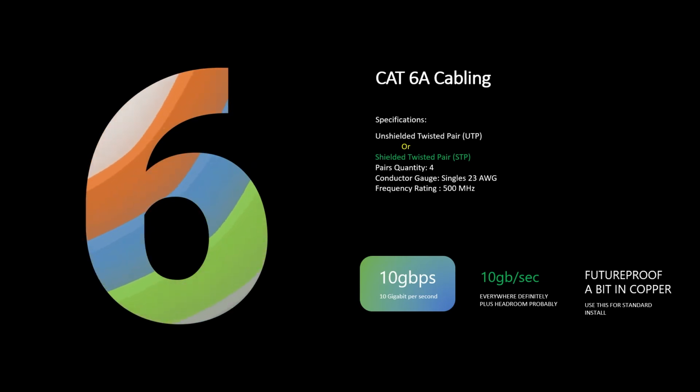Just don't look at a shielded version, because if you don't go through the proper steps and get the proper things so you can ground it all the way through the path, then shielded cabling will actually perform worse than the unshielded cabling, possibly because all the shielding and foil in there, if it's not grounded, rather than blocking out everything, may induce noise into the system. So it could be potentially worse than an unshielded cable in its place.